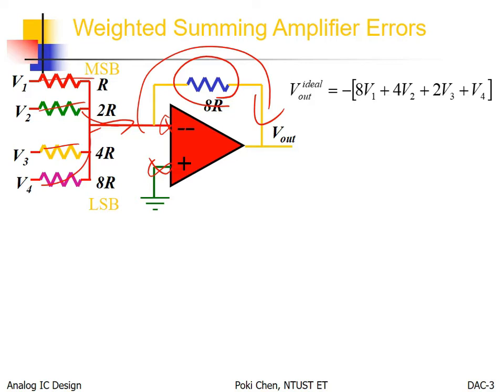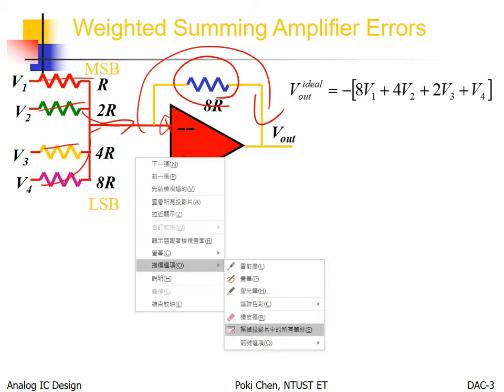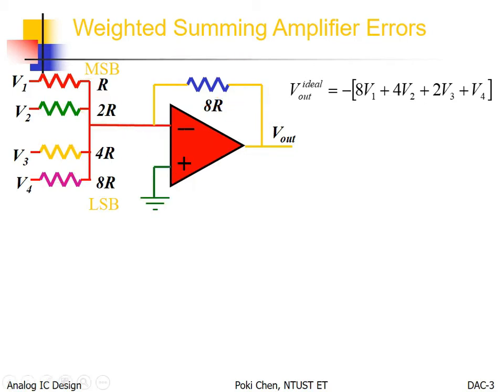So how much current will flow? Very easy: the voltage here and there should be equivalent in theory, according to the virtual ground for this terminal.